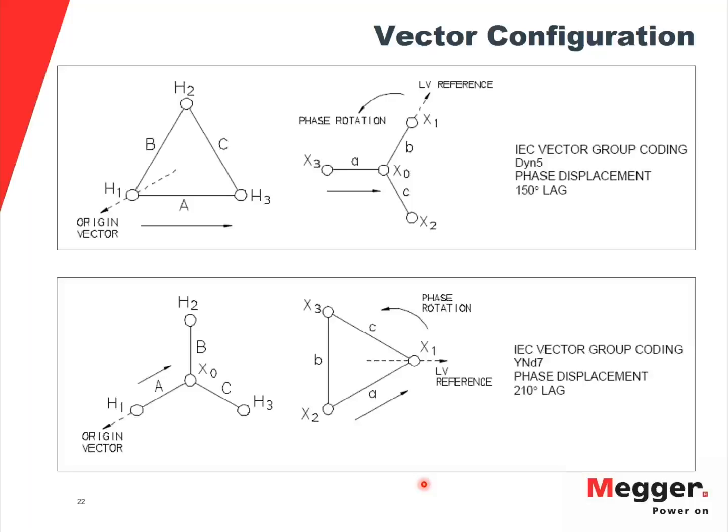But like Dinesh was mentioning during his presentation, please do not exceed more than 15% of the rated current of the winding, because otherwise you can get into overheating of the copper or aluminum material that you have, and that will affect the resistivity of that specific winding. So yes, it is critical. It's directly related to the function that you're trying to operate here during winding resistance or demagnetization.